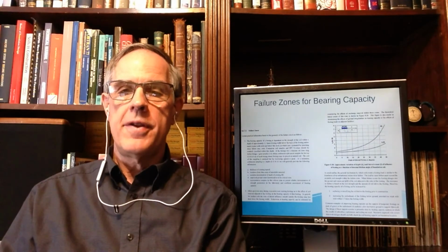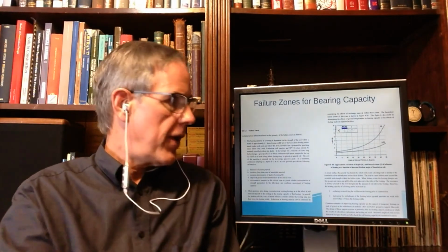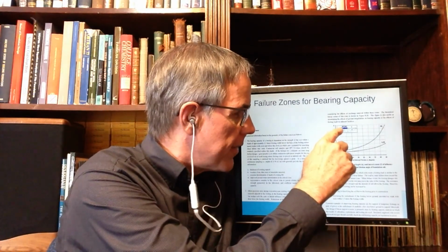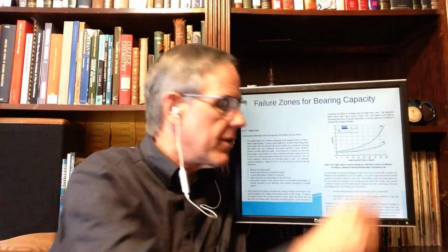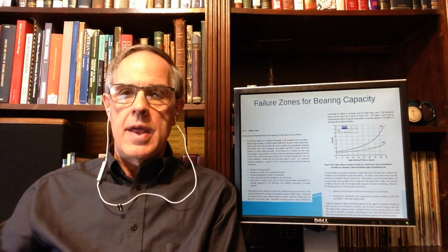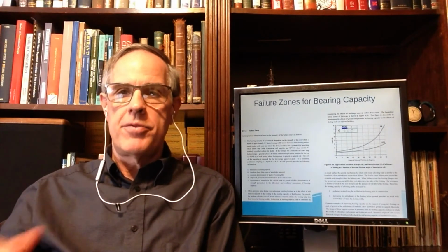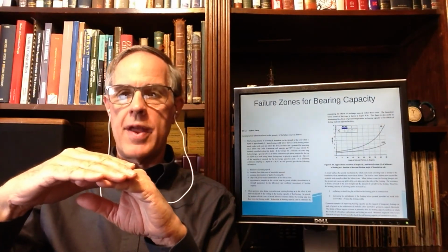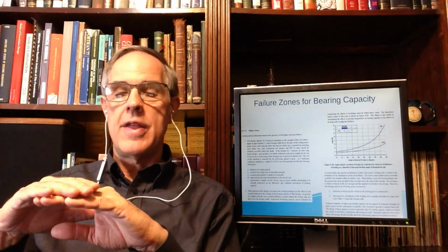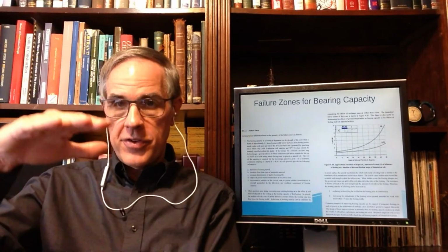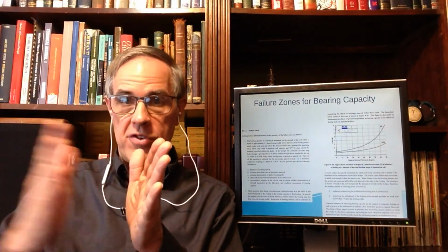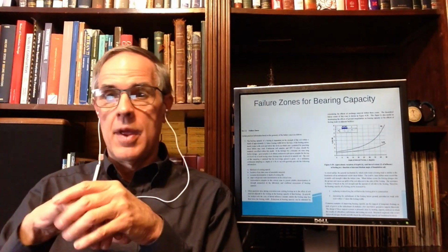With bearing capacity failure, you've got a failure surface that starts on the edge and loops around and comes back up. I'm kind of exaggerating that to make it easier to see. So basically you have to think about where that failure surface is. That can be important if you've got weak layers in this direction, and adjacent structures in this direction.